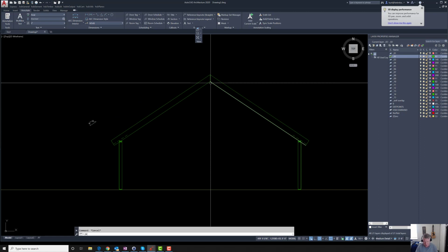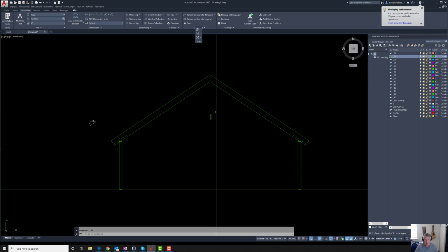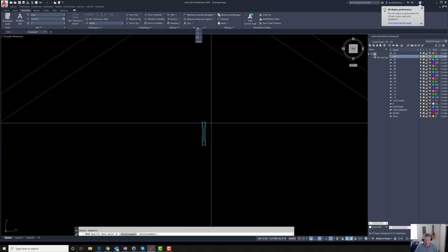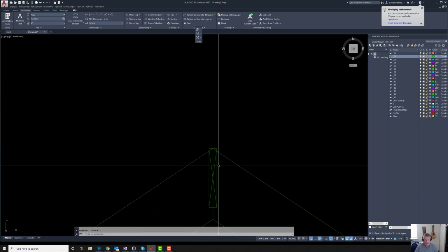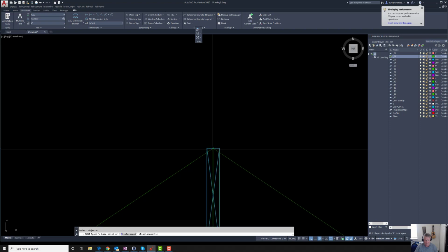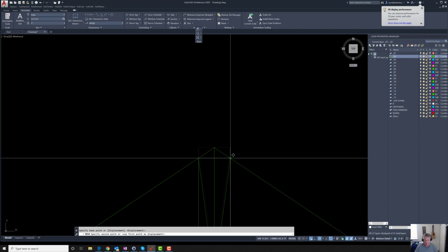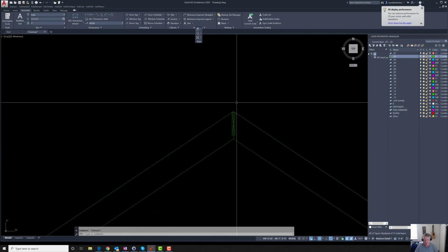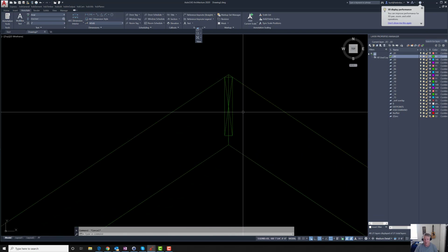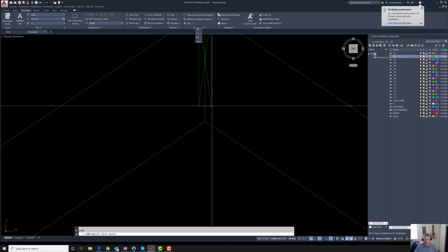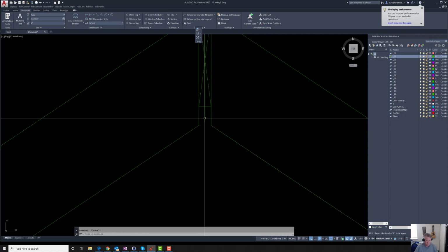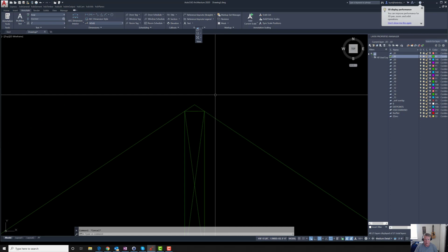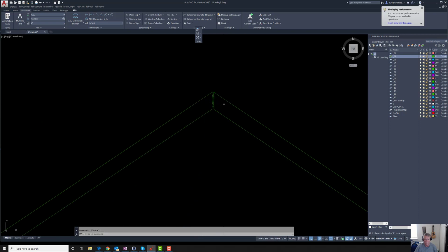We don't do a whole lot of these back in the West, but I put a 2x12 in there. I will center that right at the peak, and then I will drop it down so that we don't have to bevel or back cut the ridge for any sort of decking. So that's going to be the location of our ridge, and now these rafters will get cut off like this, probably, assuming that's the way you guys do that. And now that's going to be our kind of condition that we're going to have for the ridge.